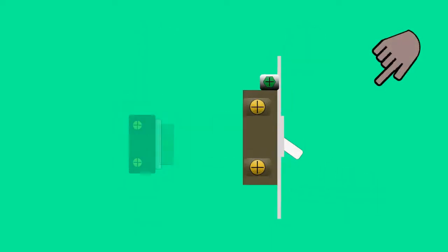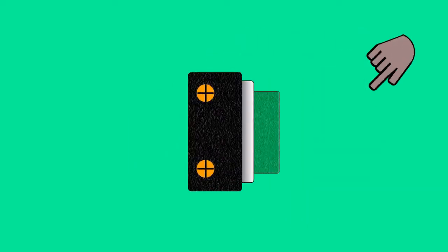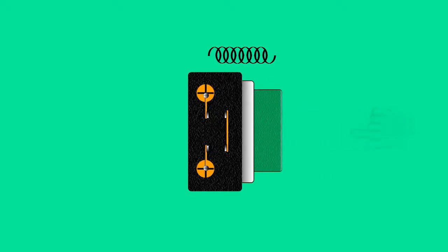Switches are identified in terms of poles and throws. The switch shown here is a single pole, single throw switch. Push buttons operate spring-loaded electrical contacts. The electrical contacts change when the button is pushed, and return to their original position when the button is released. The push-button contacts are identified by their electrical state before changing.